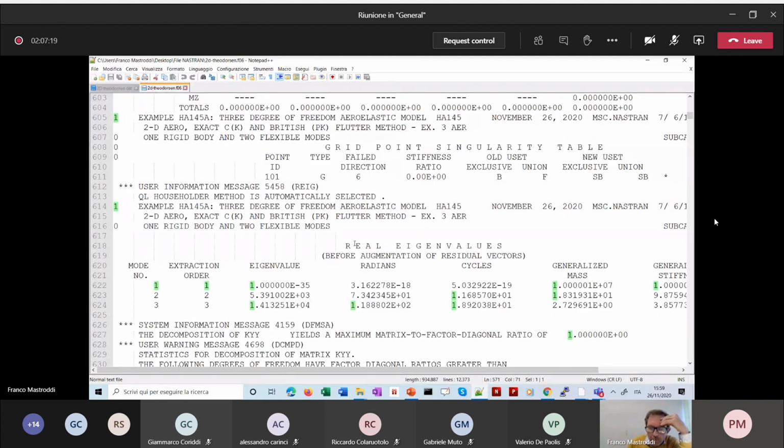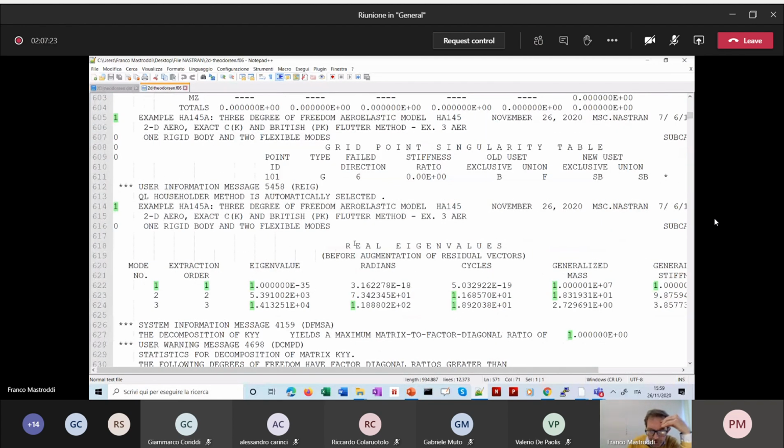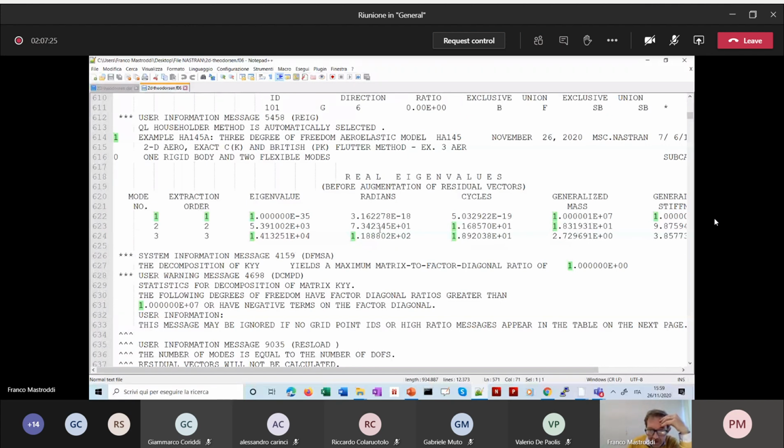And first of all, you have your structural modal analysis. This is your modal analysis. You have three modes. You asked for three Lagrangian variables, three modes. And the first mode frequency is 0. This is the frequency in Hertz. So 0 Hertz. This is 0 for engineering.